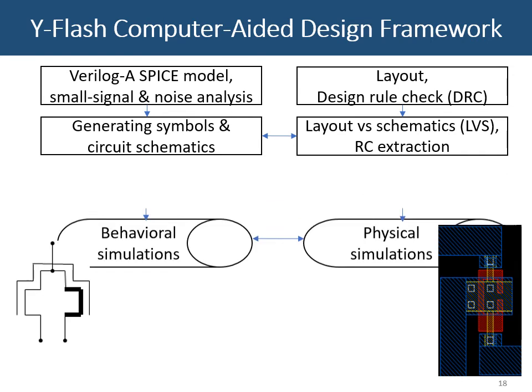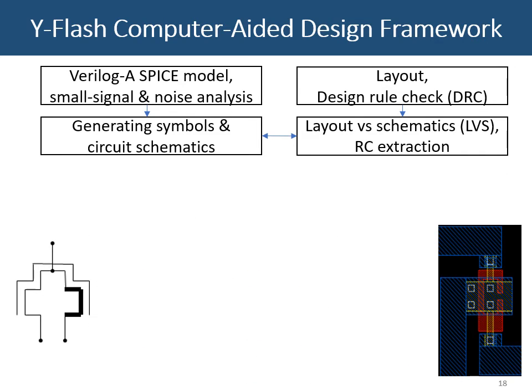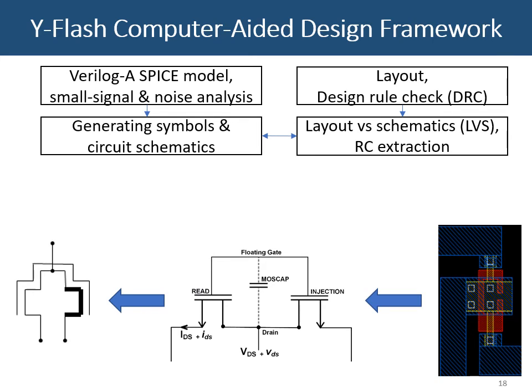In parallel to the designed schematics, a layout of the device is designed using standard GDS masks and checked for design rules using the installed library's Process Design Kit (PDK) of Tower Jazz 180 nanometer power management technologies integrated in the Cadence environment. Then, a layout versus schematic (LVS) check is performed to verify that the given layout fits the proposed device, represented using 2 NMOS transistors and a parasitic MOS capacitance.